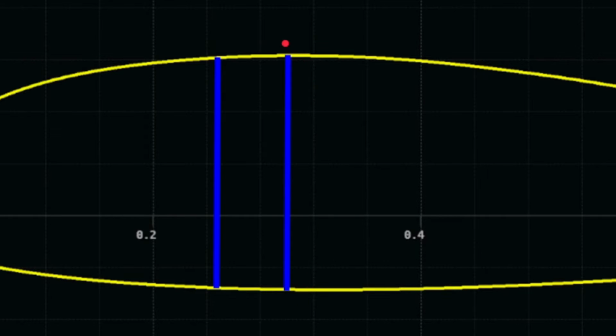So I'm going to go back here pretty close to the 31%. I think I'm going to pick about 30%. That way when I have that spar cap in here with the angle, when I rivet it down, it won't change the shape of the airfoil. And same on the bottom. It should not change the shape of the airfoil, at least not very much. So right now, that's where I'm planning on putting the spar for the UWS-4.